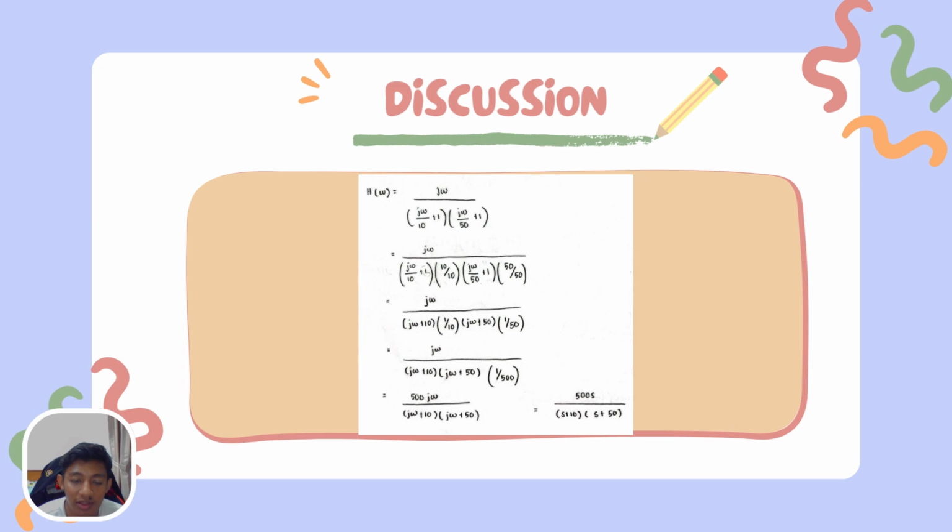Then we get the equation j omega over (j omega plus 10) times 1 over 10, and (j omega plus 50) times 1 over 50. Just multiply everything, and we get j omega over (j omega plus 10) and (j omega plus 50), and 1 over 10 times 1 over 50 gives 1 over 500. Taking that above j omega, it becomes 500 j omega over (j omega plus 10) and (j omega plus 50) in general form. Then we change j omega to s, so we get 500s over (s plus 10) and (s plus 50). That's all for me for the discussion.